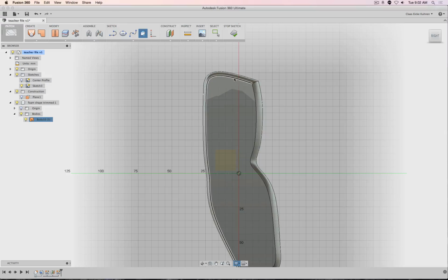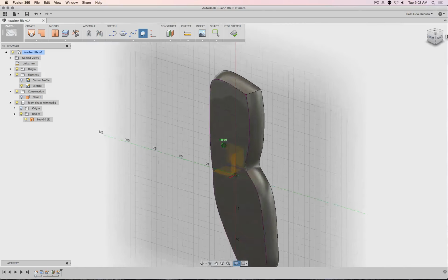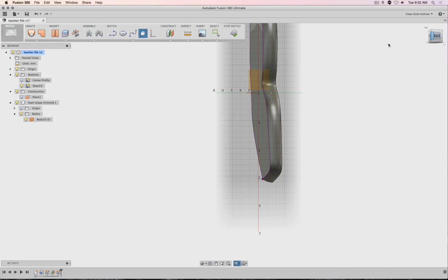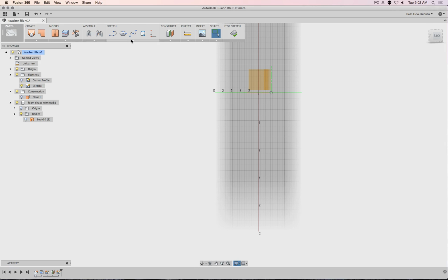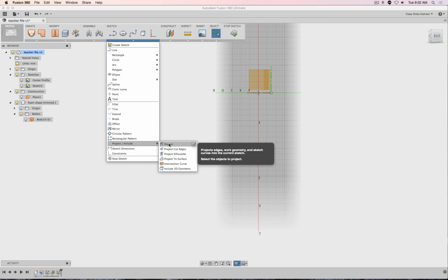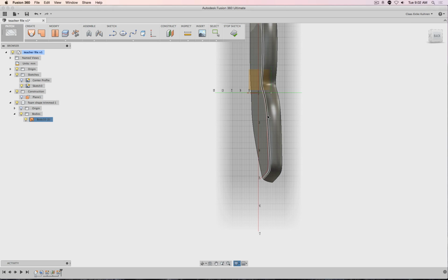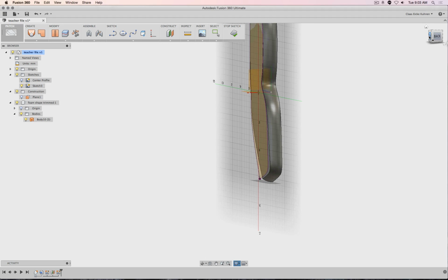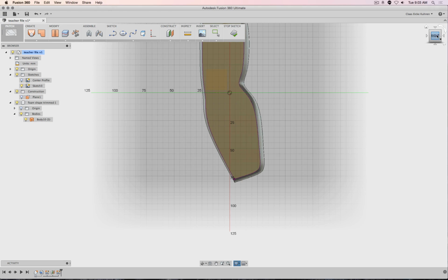And let's click this 3D include again, and we will see it works, but it's not really what I need. So you see these lines actually follow perfectly the geometry of my model. So those sketches are basically three-dimensional sketches for snapping. But that's not what I need. I want flat sketches. So I can, for example, select project and say, please project those lines into my sketch. And there you see the difference. Here's my sketch, and here's my model.